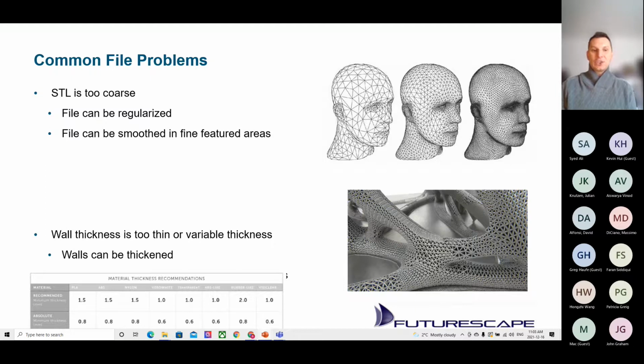You still need to plan the geometry, and they are limited in wall thickness, as an example. You can do things like thicken the walls, or add a lattice structure inside the part to remove some of that requirement for a wall thickness. There are different techniques that can be used. Ollie will be covering that in a little bit, but that's something you need to think about.